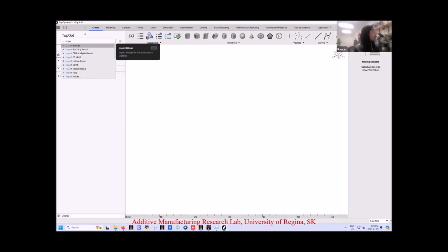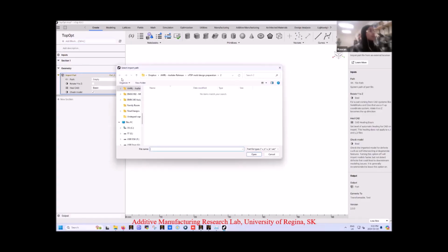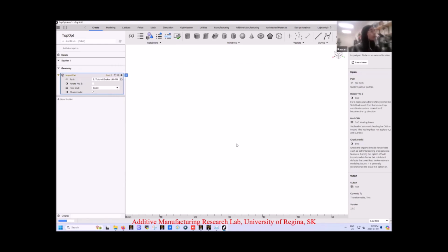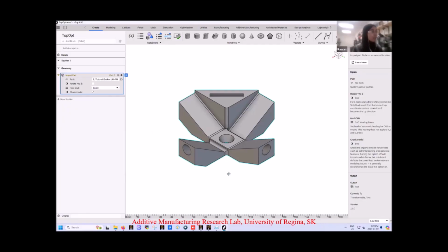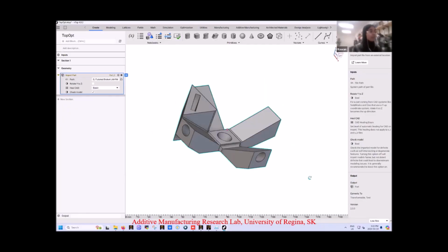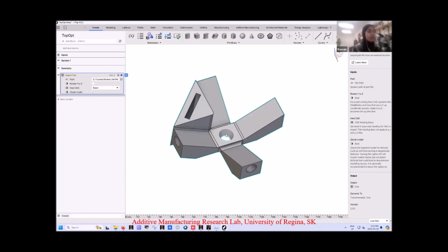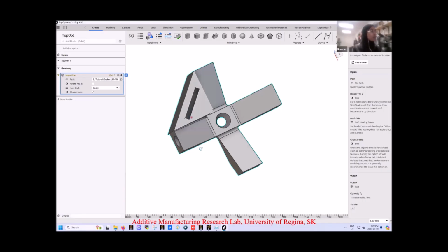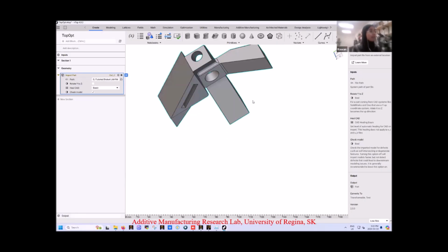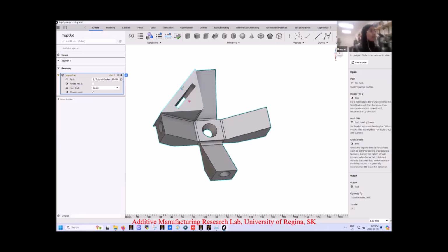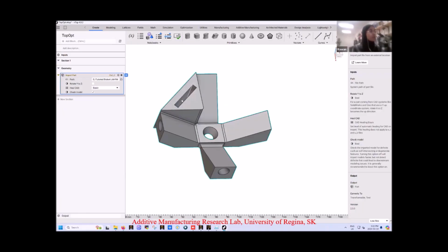So you'll have the block Import Part, just the part, and select it from the files that you have here. I already have it as a bracket design, and you can see it here. For this bracket design, we will have a mass coming here giving a load, and other loads coming from the four legs here. Then we will have the hinge or hanging structure coming here, so we'll have a displacement constraint at this area.